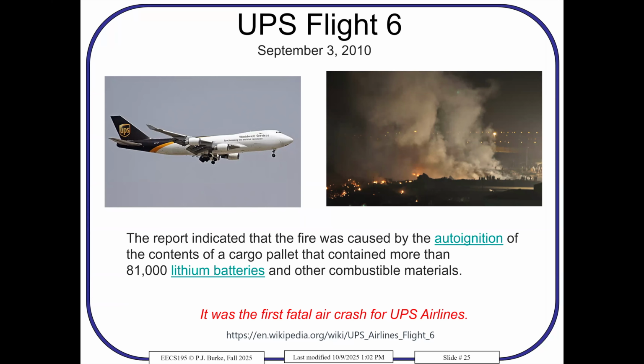But even immersed in sand, I can tell you this from the laws of physics and chemistry, if you have a LiPo fire and you immerse it in sand, it will still burn. Even if no oxygen comes in, the electrodes themselves are generating oxygen that will fuel the fire. So it's very, very difficult, even for professional firefighters, to put out a LiPo fire once it starts. But I don't advise you to try.